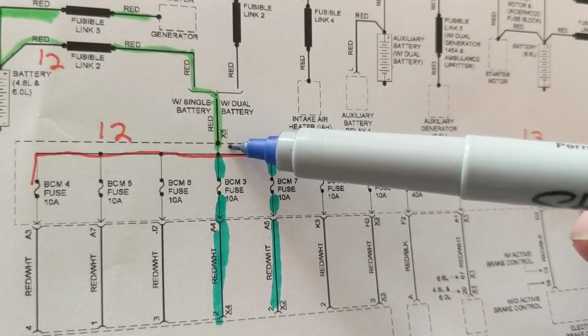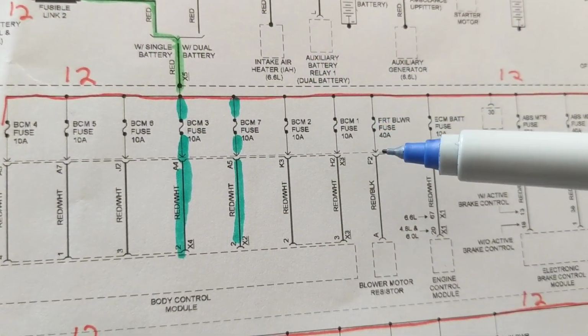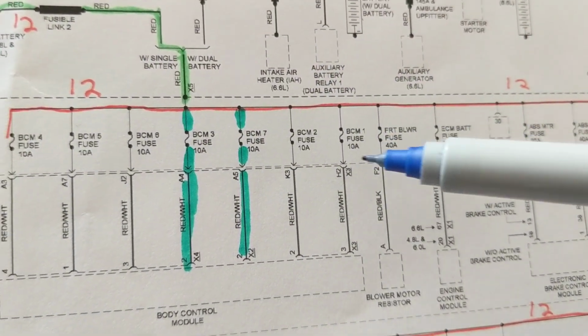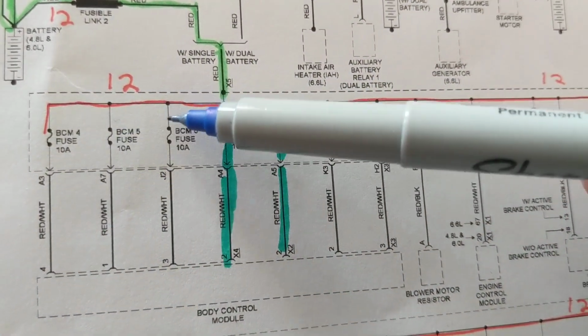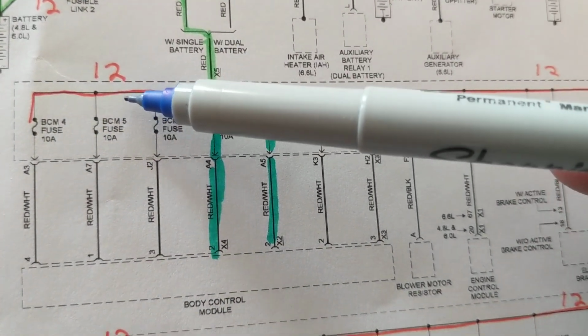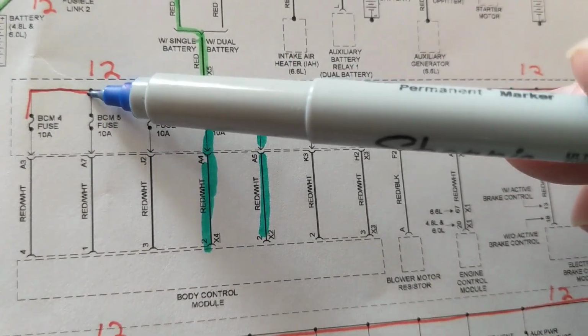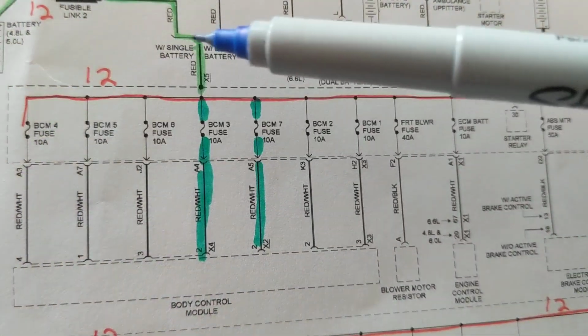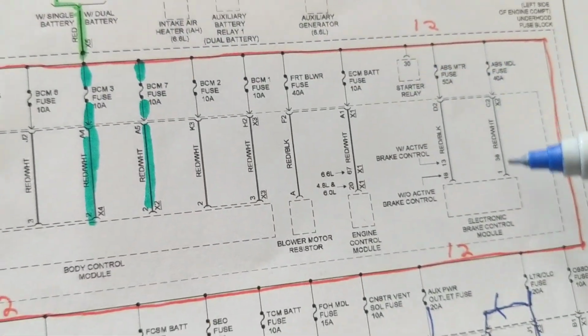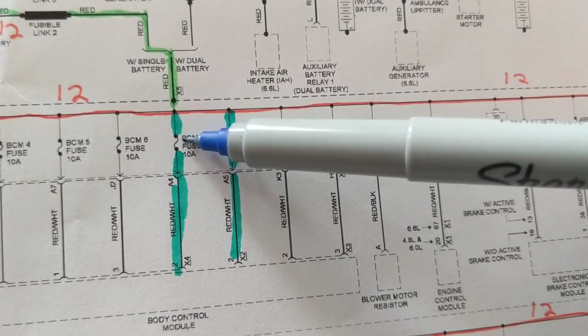Again, we come here, this is 12. Why? This is a piece of wire. You remember we discussed parallel circuits? Well, these are all in parallel. This is going 12 volts here, 12 volts here. Why 12 volts across each one? Because these are a piece of wire.